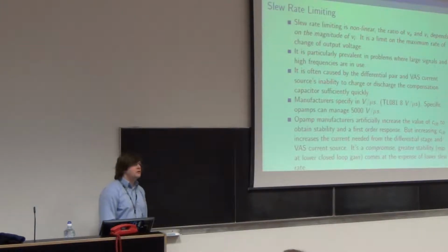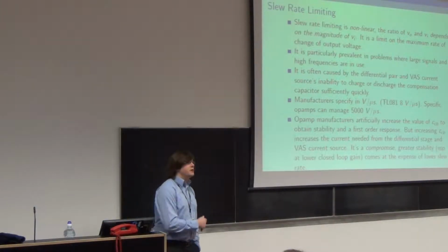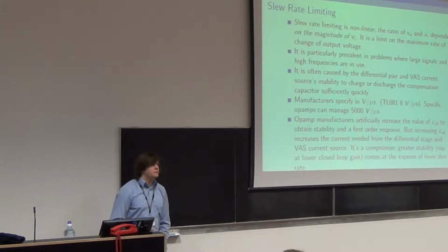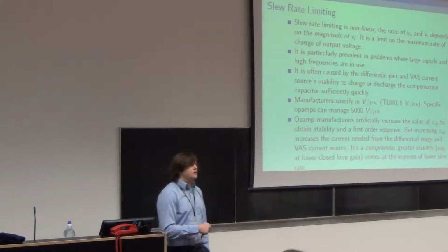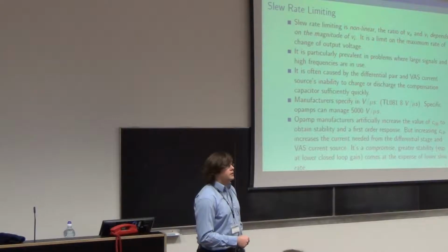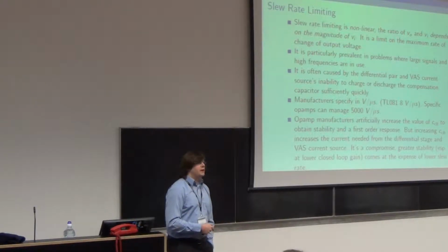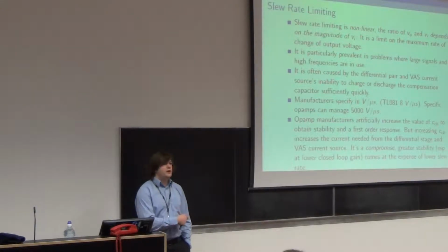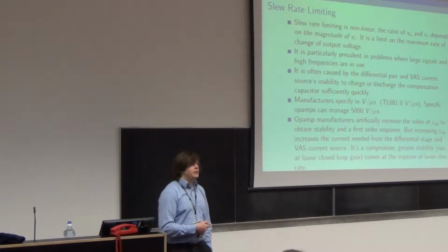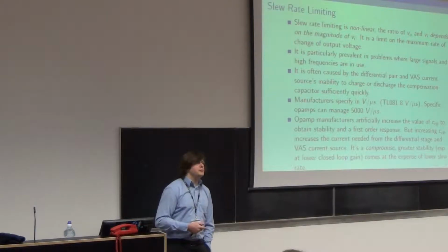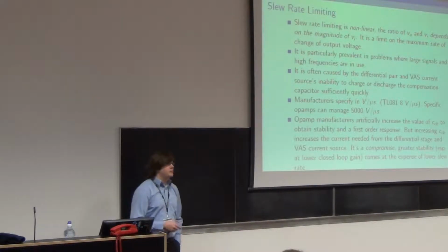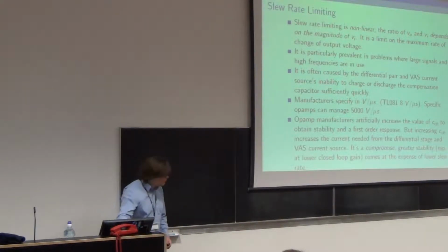If you've got an op-amp that's not unity gain compensated, you won't get a first order response, necessarily, although it might look quite first order. So if your op-amp is an op-amp where you buy it, and you have to compensate it yourself, and you get some slew rate limiting, or you choose to look at it, it will not necessarily be an exponential response to a square input. It might have some other shape. In fact, there's a good chance there'll be some ringing, which is, everybody happy with the idea of ringing?